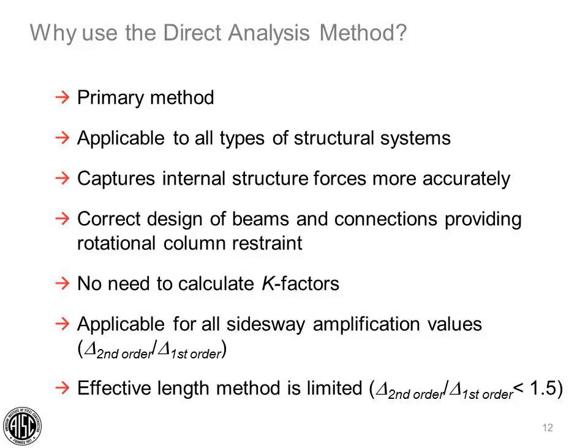The direct analysis method is applicable and accurate for all ranges of second order effects. And for frames with large second order effects, when the second order effect is greater than 1.5, the effective length method or the first order analysis method are no longer permitted, and the direct analysis method must be used instead.